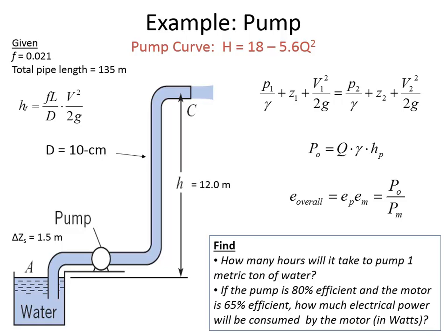Yeah, but would you use the system curve to get that Q value? We could. Excellent question. I was going to mention that you could use either the system curve or the pump curve, and you're going to get the same thing. So let's just prove that to ourselves. If we had substituted into the system curve, then it would be 12 plus 25,101 times Q squared, with Q being 0.0155 cubic meters per second.